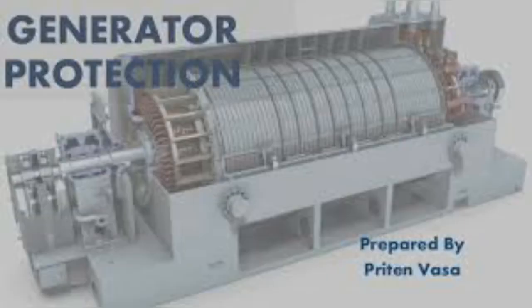What is generator differential protection? Differential protection for a generator is mainly employed for protection of a stator of a generator against earth fault and phase-to-phase fault. Stator winding faults are very dangerous and cause considerable damage to the generator.